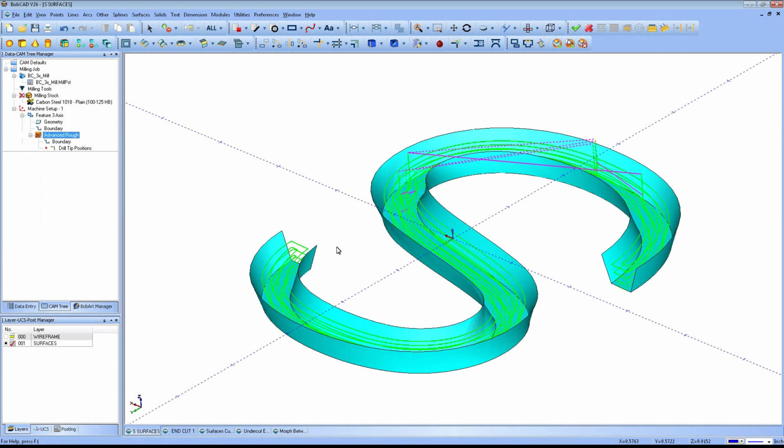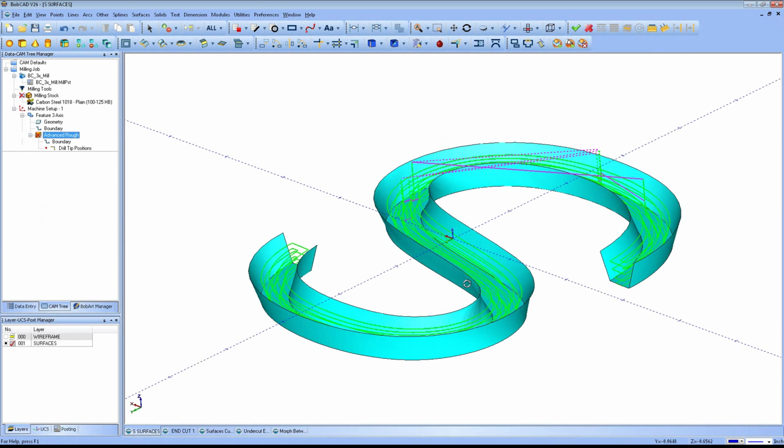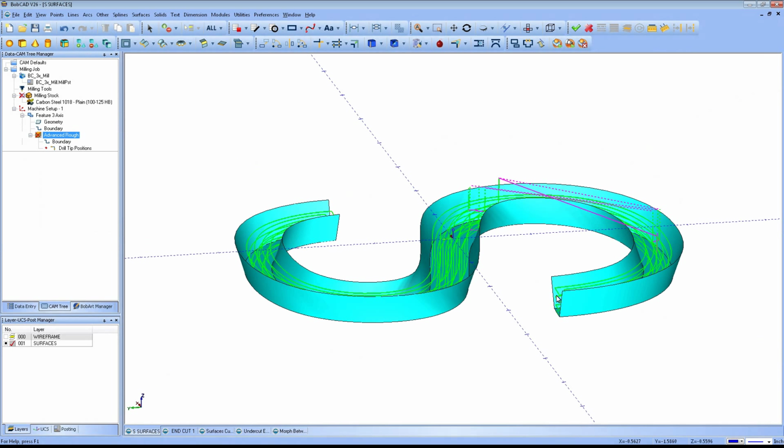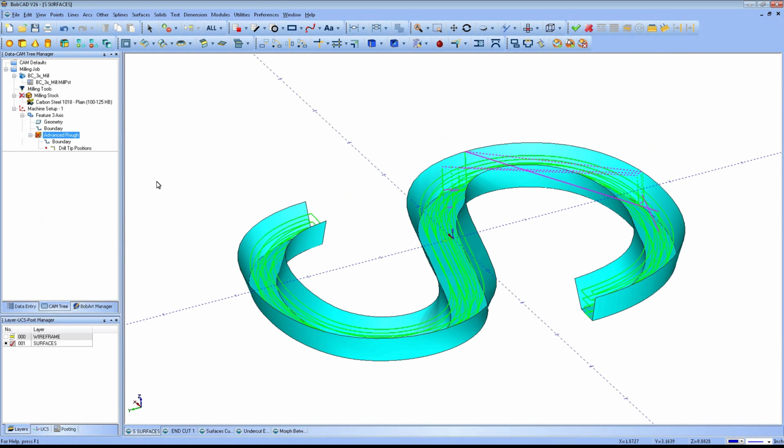As you can see, the advanced roughing is going to follow the shape of the channel, but it also turns. So if this was a wall here, or if you wanted the tool to come out the side of this, you would have to extend it out, and it's going to turn. It's going to leave different types of cutting and different loads on here, where you might want just that continuous back and forth cutting motion. It also wants to start, as you can see, in the middle versus on the end, and do connections at that point. So let's take a look at how to apply a multi-axis toolpath to this to output in a 3-axis format to get the type of cut we're looking to do.